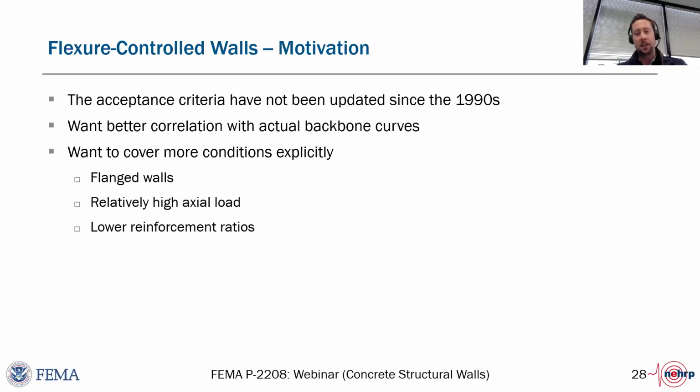Because there were cases where you have existing buildings that really didn't have the reinforcement that we'd like to see today. And at some point, again, you had to treat it as force controlled. So the issue with those force controlled actions is that you came from having maybe little but some deformation capacity past yield to all of a sudden it's a step function where now you're force controlled and you basically don't allow any inelasticity. You can't even go up to the average strength that you'd expect. And that becomes really difficult to deal with